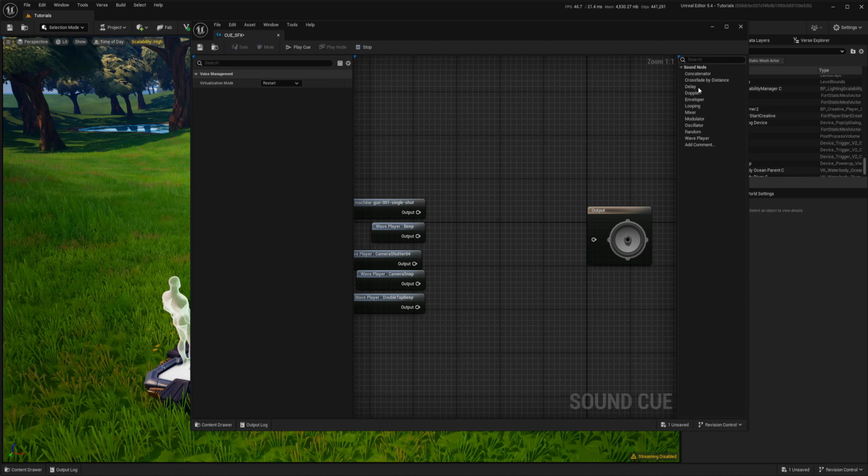First of all, what we want is to create an audio cue. So we go to Audio, and then Sound Cue, not Audio, yeah, Sound Cue. We can name it, let's say, Cue SVX. Double click to open it. We have an output and we need some input. The input will be all our audio, so we can select everything and drag and drop it here.